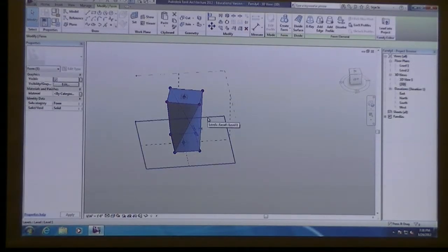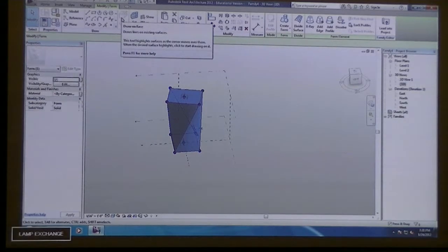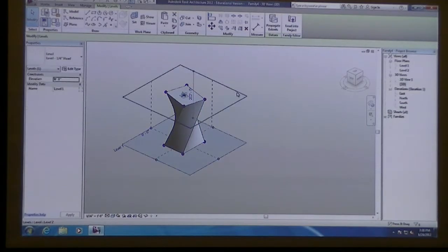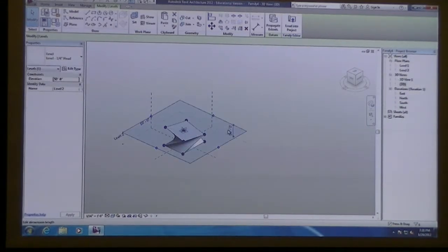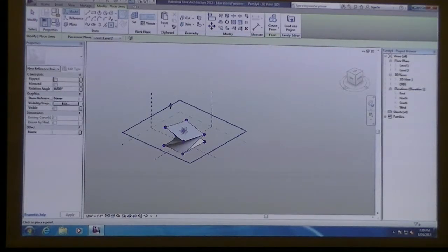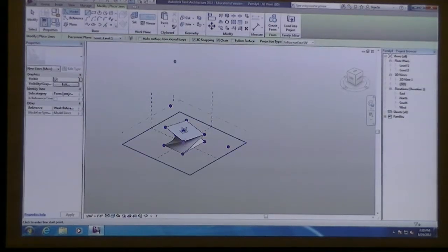So anyway, that plane surface would be a good way to create a platform. If you just had a series of platforms that were associated with it, like a tower, you could do your walking path. You could also set it up where, if you have one level to the other, I could actually have a spline. Let's see, if I create a point on level 2, and then do another point on level 1, and then if you create a line, make sure 3D snapping is on.